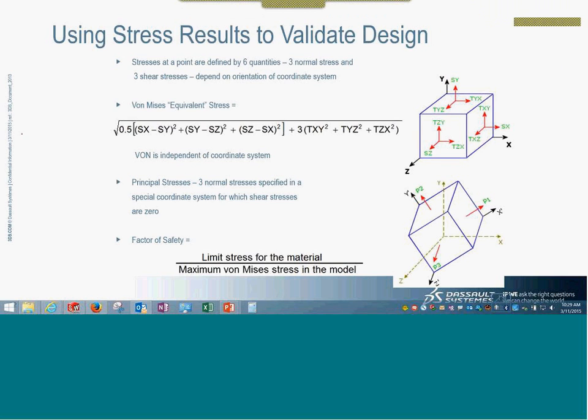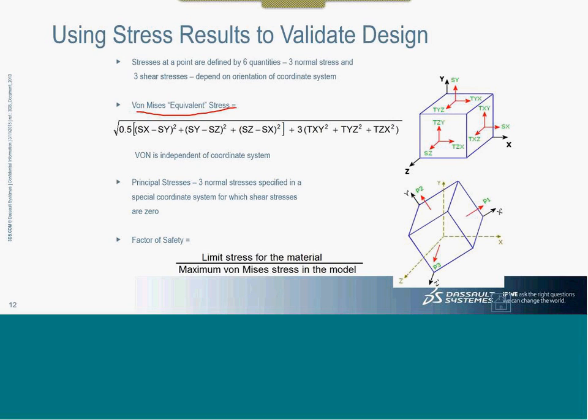Next, I am moving directly into stresses, or the kind of outputs we are getting from this software. By default, blindly or without much thinking, we are seeing only one result, which is called von Mises stress. Am I right? We end up thinking of only this stress, and of course we do have stresses which are equally important, like principal stresses, shear stresses, etc.